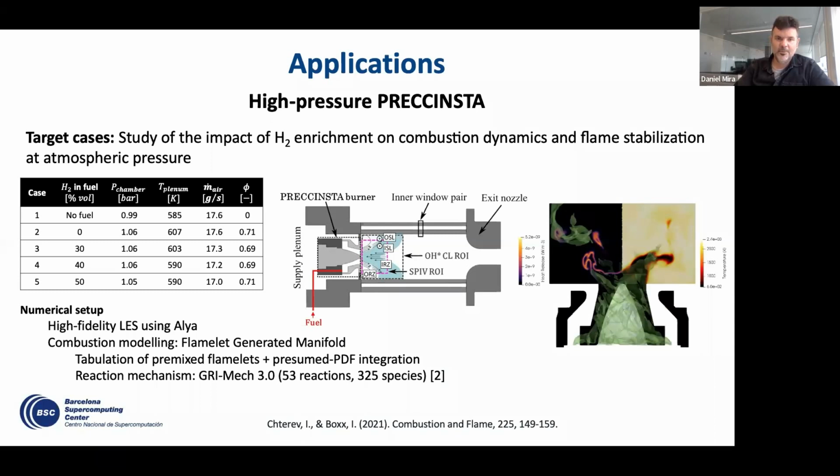For these simulations, we conduct LES with the tabulation of laminar premixed flamelets and using presumed shape PDF. For this, we use the GRI mechanism for all the calculations.